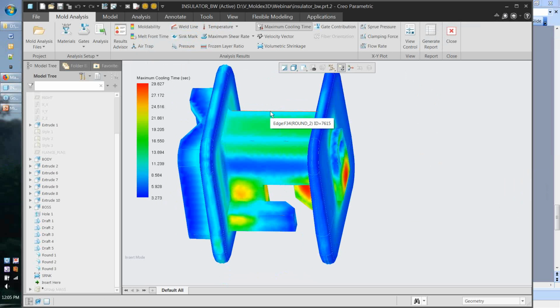That being said, when you have the system calculate maximum cooling time, it will calculate all the way to the material manufacturer's ideal target eject temperature. That may in fact be notably longer than what many people actually use as a cooling standard.